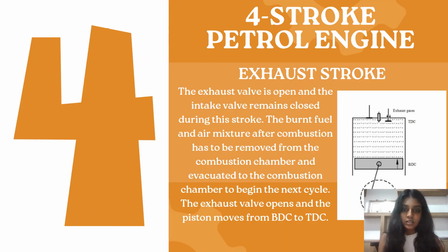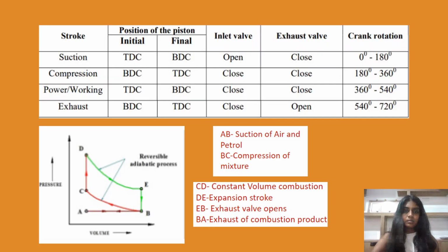Finally, we have the exhaust stroke. The exhaust valve is open and the inlet valve remains closed during this stroke. The burnt fuel and air mixture after combustion has to be removed from the combustion chamber and evacuated to begin the next cycle. The exhaust valve opens and the piston moves from BDC to TDC.